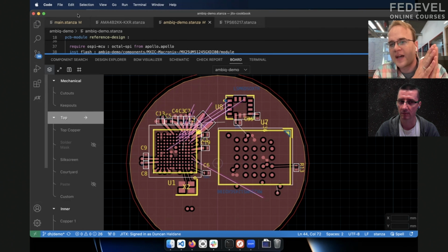So we were talking a bit about high speed earlier. For a high speed connector, you have this landing pad and you have to void underneath it. Like if you have a DIMM socket, for example, you have to route around that, right? You have to make sure that your reference is not going to be significantly impacted. So that, as well as really solid features for via stitching. If you make something like an RF trace, like a conductor-backed coplanar waveguide, you want to guarantee that these vias are going to be there, which is much the same problem. You say I made this impedance structure assuming this geometry will be here, and now I'm going to make sure that it is in fact there.